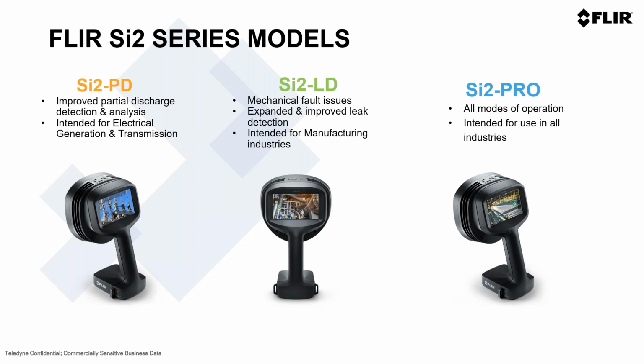The camera will find where there's a potential mechanical fault and give the decibel level of the fault, where it allows you to use the comparison method or use our analytics with the crest factor and kurtosis statistical indexes, and make your own decisions on the maintenance of your systems.